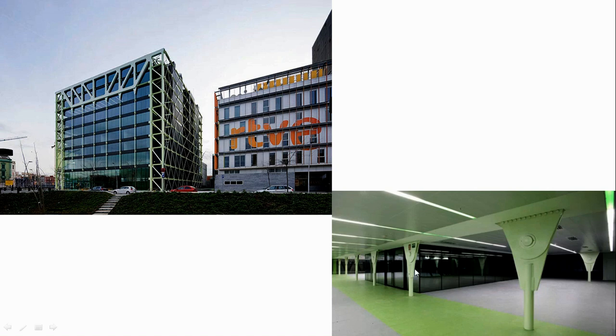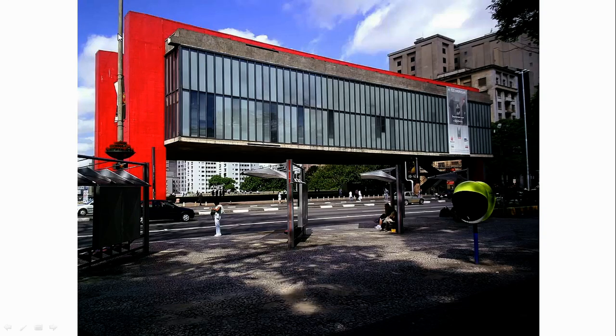And there you can look at that inside. This is a nice pin joint connection. Why would you do that? Well, you do it for a couple of reasons. One is that if you had to span the floor from here to here, it would be a very deep section, wouldn't it? It's quite a big span to depth ratio. So it pushes all the building up higher and higher and higher if each floor had to span. Instead, all the spanning, all the load, if you like, is taken back up to the top there, and they're hung from it, which is rather nice.